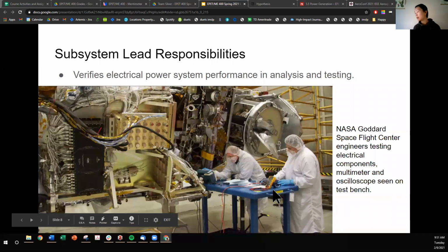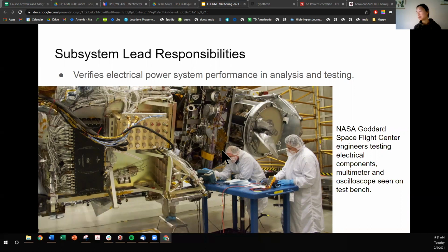They have a lot of test procedures that they printed out, and they're most likely checking out this large system. So yeah, just making sure that the pin-to-pin connections are actually connected, that there's not a break in a wire, that they're at the right voltage, that when the system is running, they're drawing the right amount of current, etc., etc.